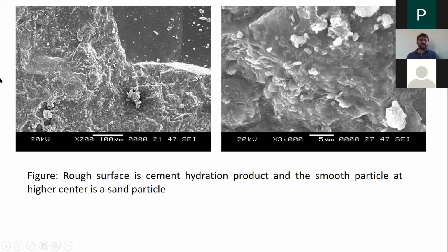These secondary electron images are very good for the samples which are not polished. For example, once you do the compressive strength test, you can take those samples only, such kinds of samples, after sputtering and all, you can see the images. Based on this, you can see the depth, where are the voids, all that study you can do. This is only qualitative analysis. If you want to go for quantitative analysis with SEM images, then you have to go for backscattered electron images.